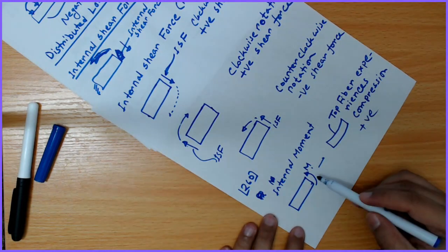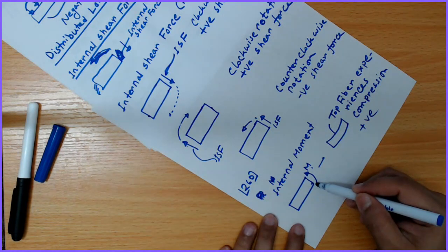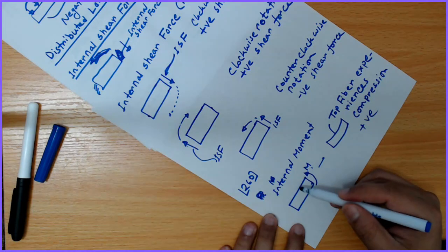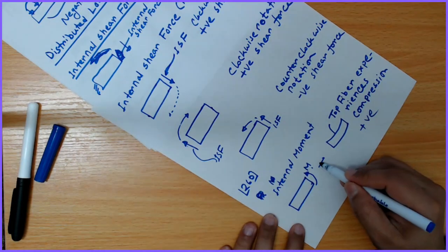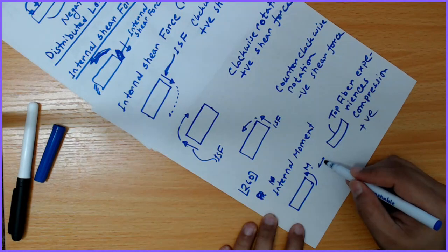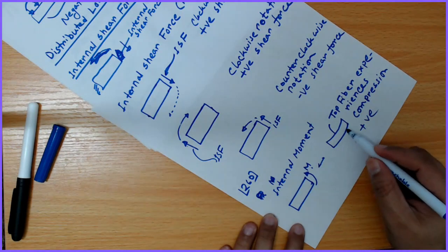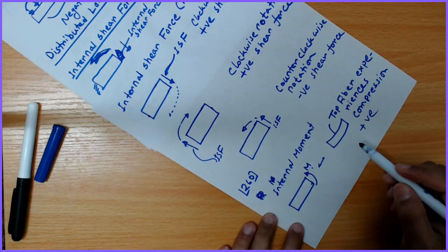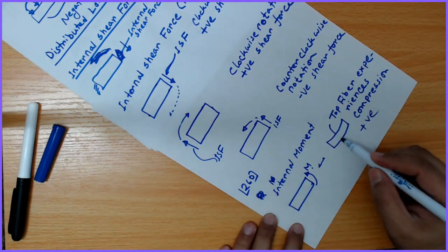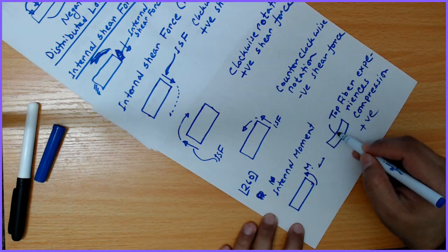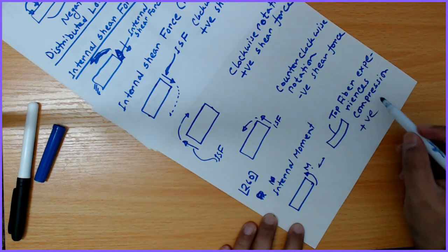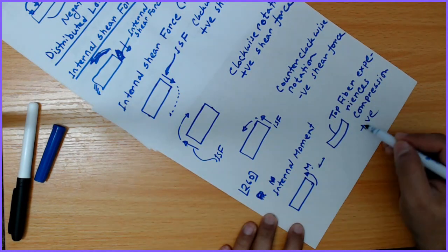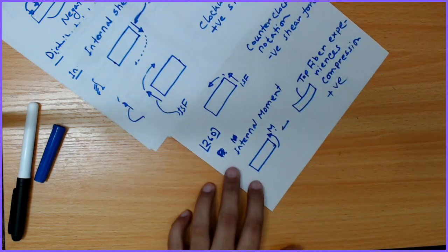I'm repeating, if the moment is in such a direction, clockwise or counterclockwise, it doesn't matter, if the beam bends due to the moment and the top fiber experiences compression, then this moment is positive. So this is one example.